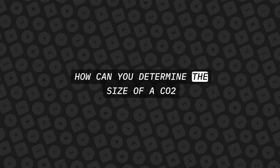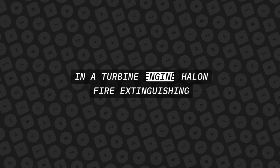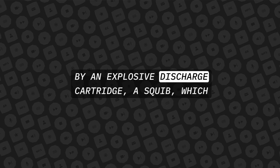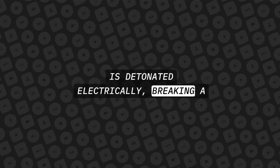How can you determine the size of a CO2 extinguisher? By weighing it. In a turbine engine halon fire extinguishing system, how are the bottles discharged? By an explosive discharge cartridge, a squib, which is detonated electrically, breaking a frangible disc.